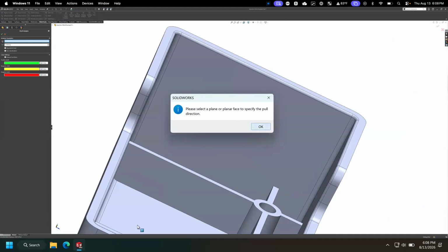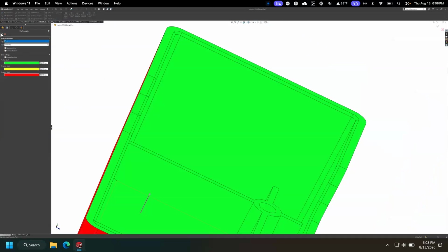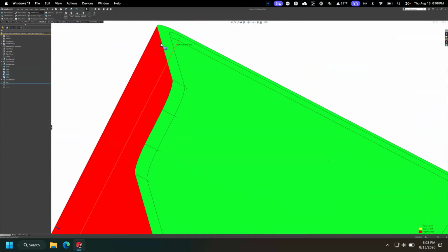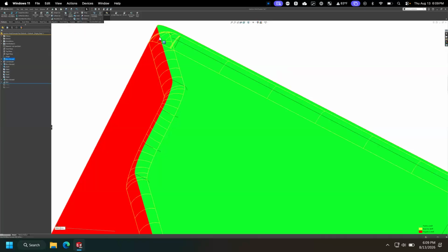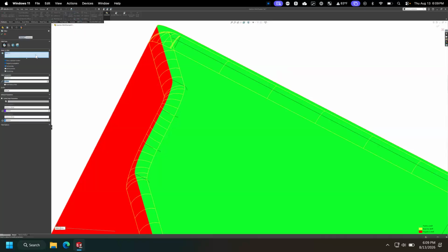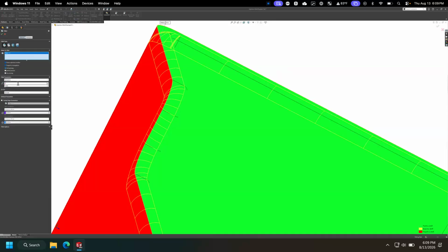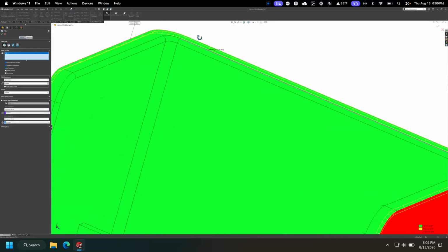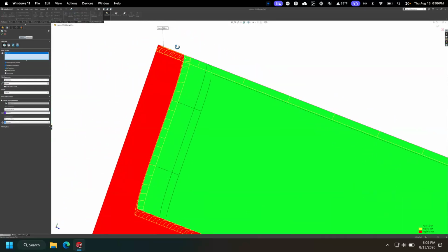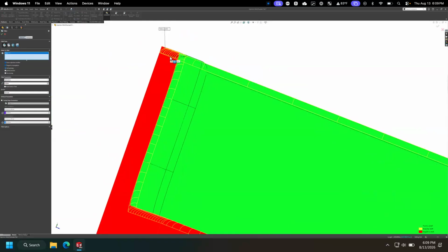this face here is sharp because it's my parting line. But if I did add a fillet on this edge, it'll create a weird situation where if one part of the mold has to have that, then it's like an infinite sharp on the tool.